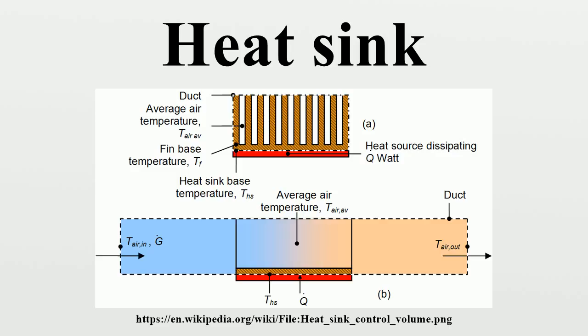Copper has excellent heat-sink properties in terms of its thermal conductivity, corrosion resistance, biofouling resistance, and antimicrobial resistance. Copper has around twice the thermal conductivity of aluminium and faster, more efficient heat absorption. Its main applications are in industrial facilities, power plants, solar thermal water systems, HVAC systems, gas water heaters, forced air heating and cooling systems, geothermal heating and cooling, and electronic systems. Copper is 3 times as dense and more expensive than aluminium.